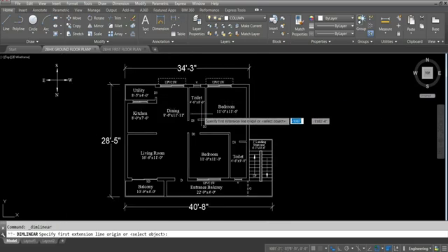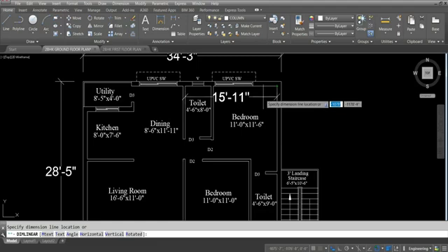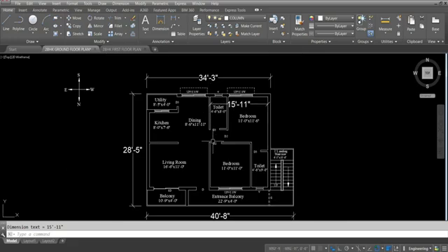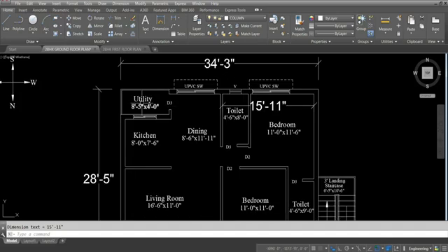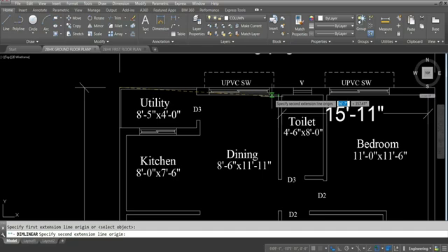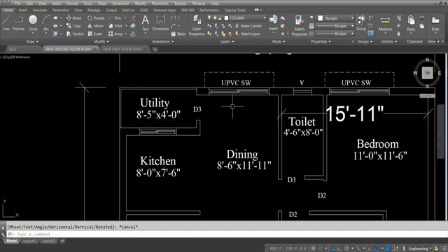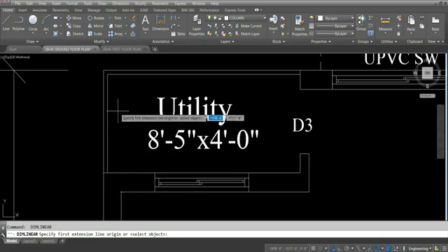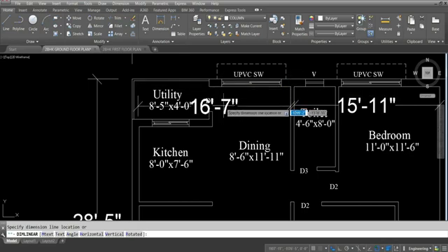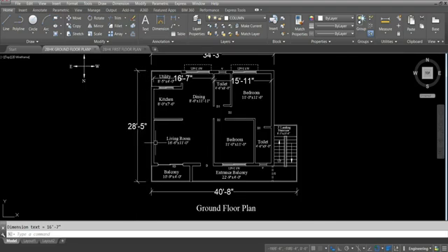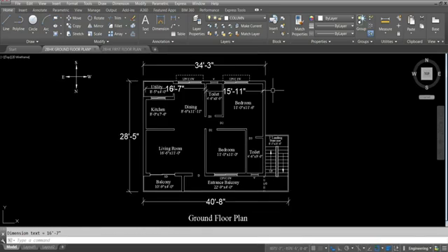So we have to check next distance. So if we check this point to this point, it is 15 feet 11 inch. So yes, we can provide another column there. These internal walls are partition walls, but still the width of the column will be inside this wall. So next, this point if we provide second column here, and the last one if we provide here. No, this distance we will not take end to end, because column, this point to this point, this distance 16 feet 7 inch. So here also one more column we can provide. So this side we will provide 3 columns. This side also same. This column will go in same grid line. So all the columns should be on same grid line.